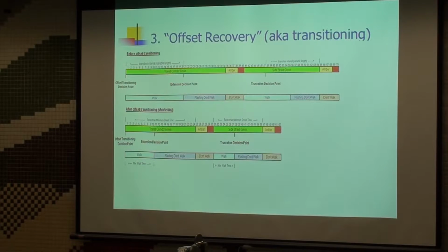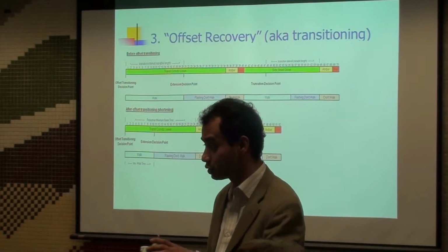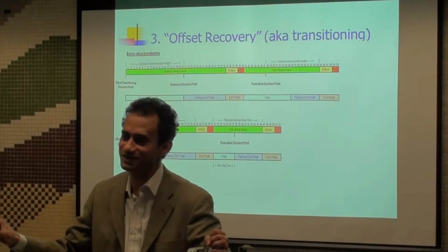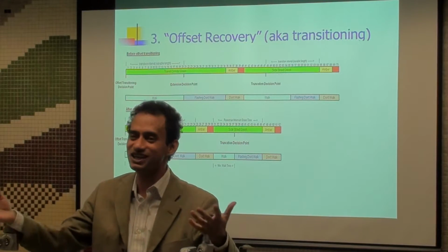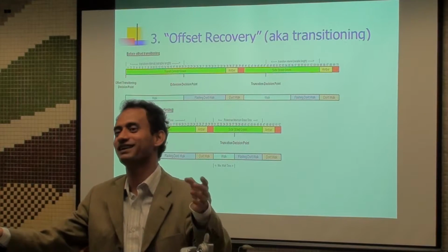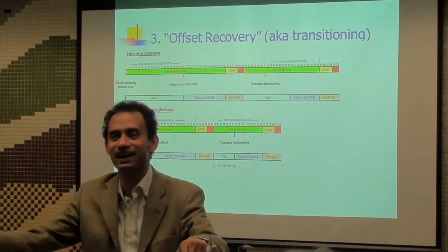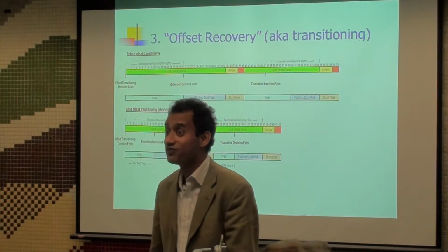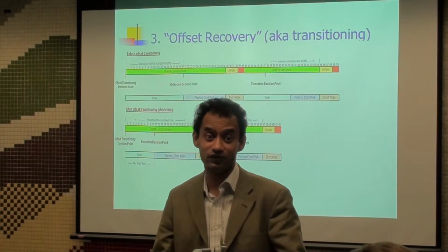And we can test those kinds of things in micro simulation tools. For example, this lab is probably within a month getting all those things. We have ordered that. So you can also test, if you are changing that signal timing, how much you are improving and what the delays will be. So VISSIM, V-I-S-S-I-M, is for this purpose.